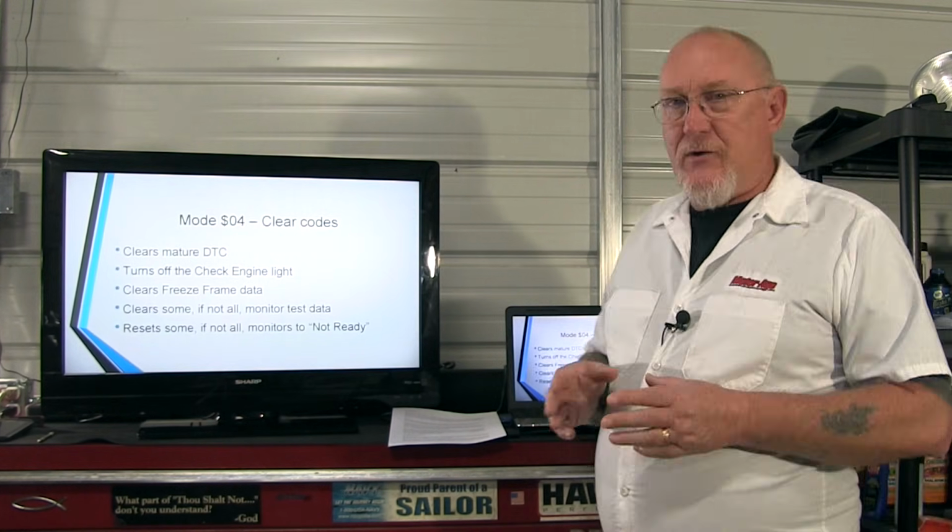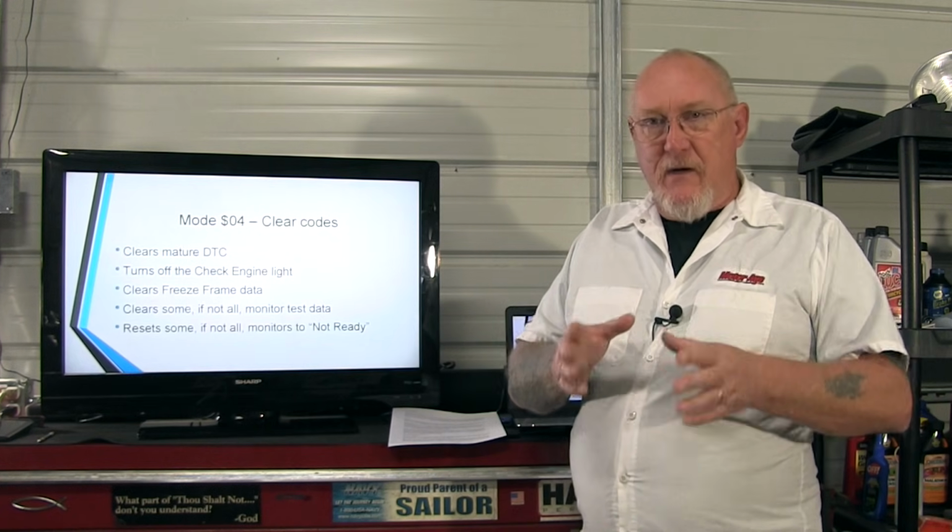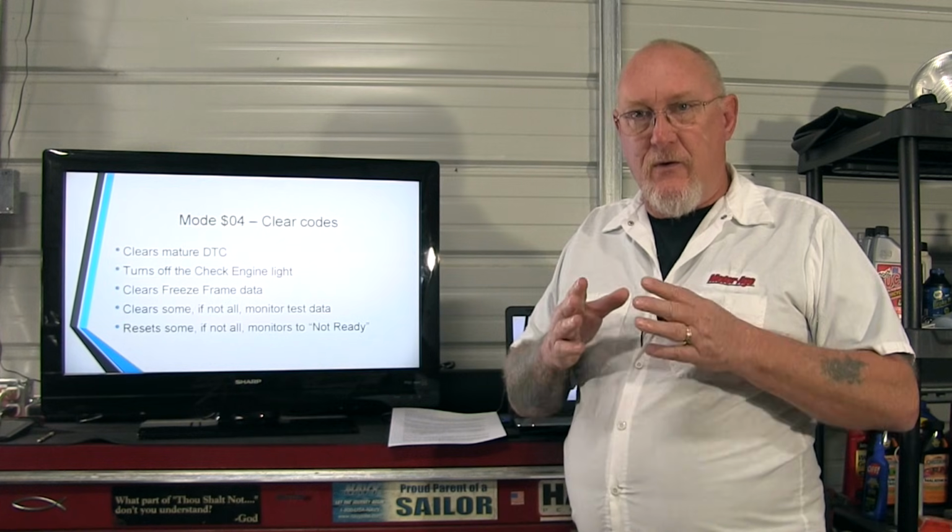This is one thing you want to make sure of, again: that you don't clear or turn off that check engine light until you're absolutely sure you're done and that you're ready to make that test drive and verify that repair.